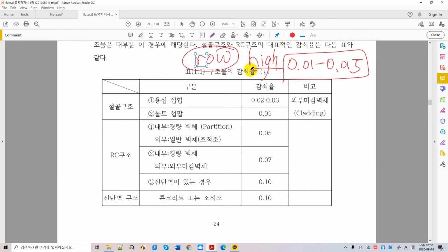When you get to the Midas project later, your building never stops, or your building's deflection is very high, so you cannot stop, you cannot start, and you cannot finish your building's motions. The reason is your damping is very small. Okay, that you need to think about putting some artificial damping. So, in reality, understanding and determining damping ratio is very important.